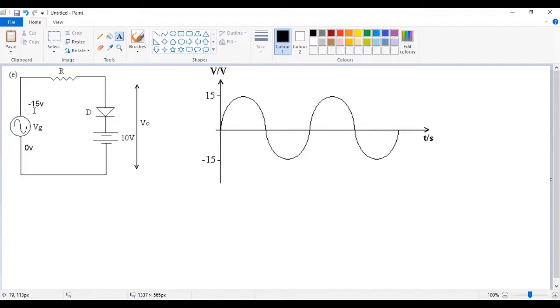Okay, so let's take this approach where we assume that the terminal at the lower end is always grounded at 0 volts, and as the waveform has different values along the sinusoidal waveform, it's the magnitude of the upper terminal which is changing. It could be plus, it could be minus, depending on where you are on the waveform. That's an important approach to solve this type of problem.